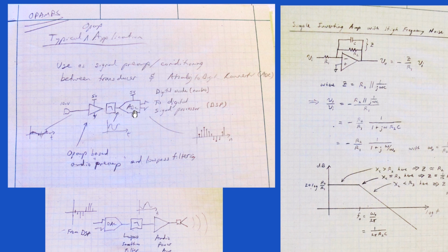And what we get out of the ADC are a bunch of numbers like this. And this, you can probably see, looks like a sine wave. So I got rid of the noise, but I digitized this sine wave after the low-pass filter, and I get out a bunch of numbers that basically map out a sine wave. And then through the magic of digital signal processing, we can do the same thing we do in the analog domain with filters and S domain and so forth.